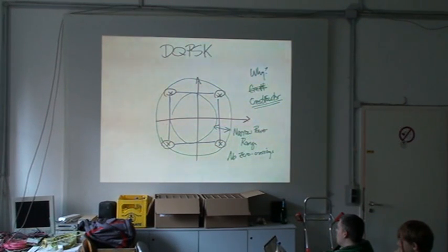GMSK is exactly that. The DQPSK has a crest factor that's not that far off of 1, because the signal is confined to this sort of annular ring that never goes through the origin. So the reason you do this, to dig a little further into why you want to avoid crest factor, has to do with the way that power amplifiers are built in the real world.